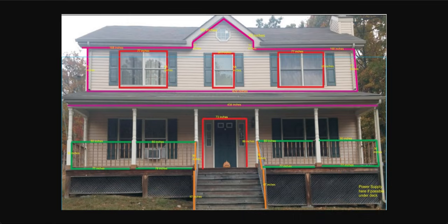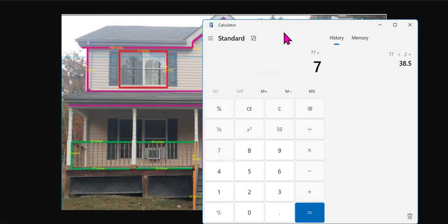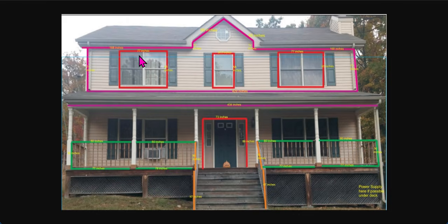All right, now we also need these numbers when we're calculating the total number of pixels required. Of course, if you've got, let's say, 77 plus 77 plus, let's say it's 58 plus 58, that's how many inches are around that window. How many pixels will we need? Well, we divide it by our ultimate spacing, 2-inch in this case, and that's 135. So we would need to accommodate that for the entire design.